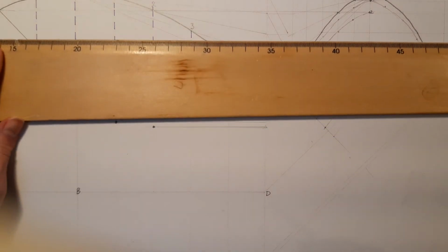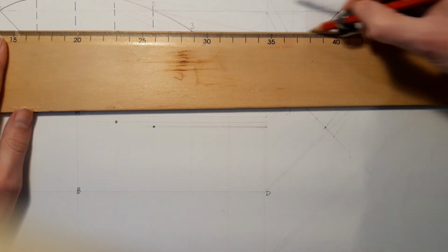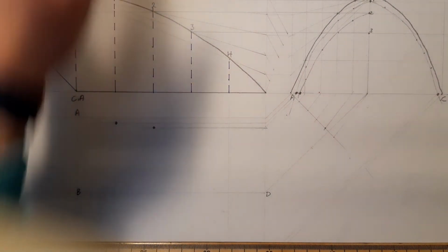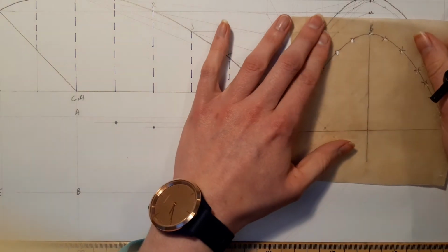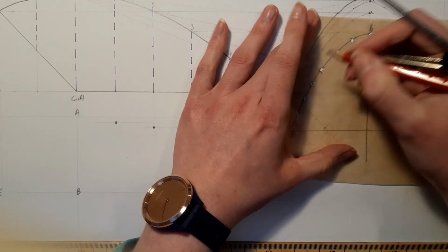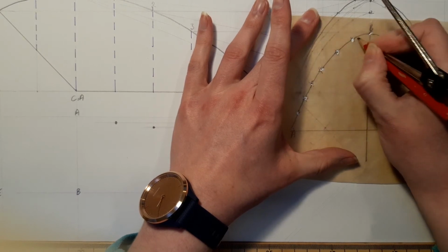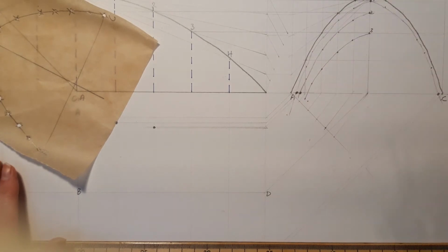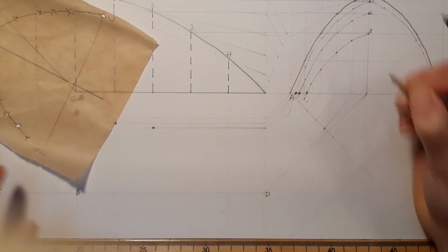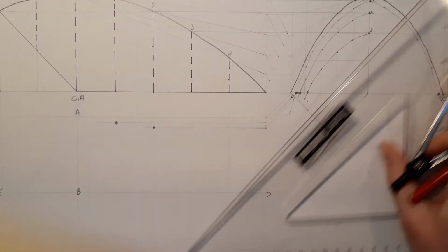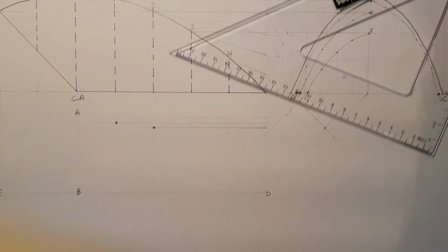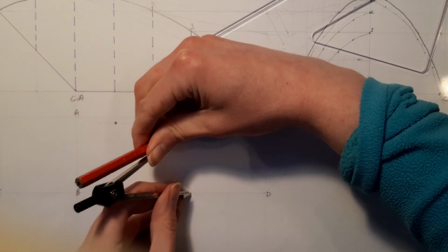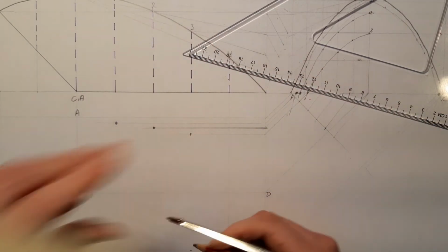I'm going to take the third height now, bring the third height across. Okay, height 3. Get my tracing paper for a third time, put B on 3, making sure it's on my center line, plotting all these points again. Okay, as you can see, my third curve coming in, and it's the point on the actual ground that's important. Bring it across at 45 degrees. Transfer it onto the line 3. Take your compass and transfer it to the other side to make it symmetrical.